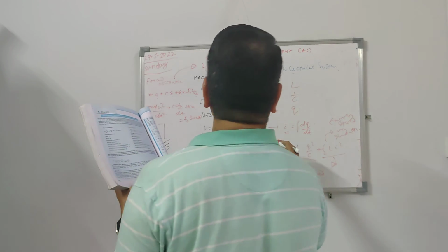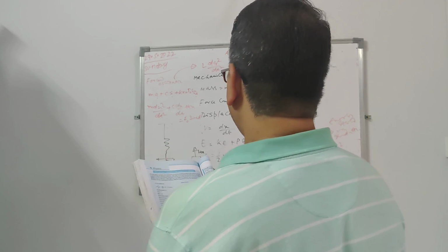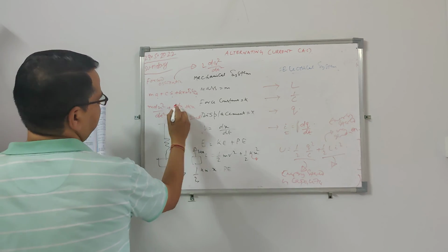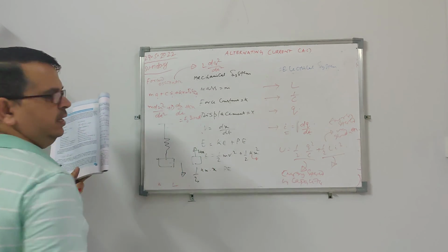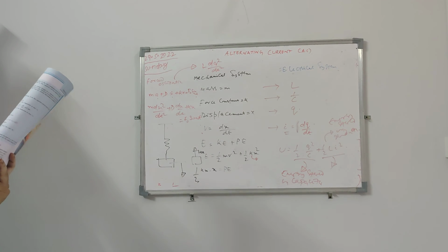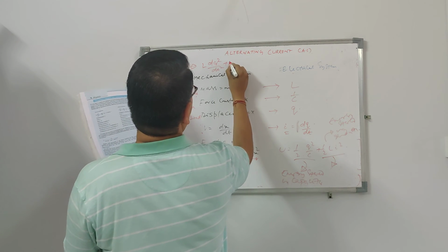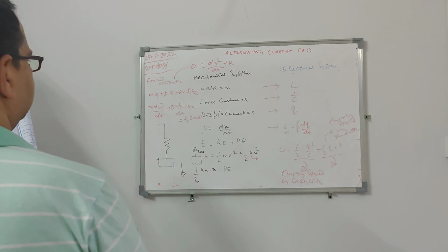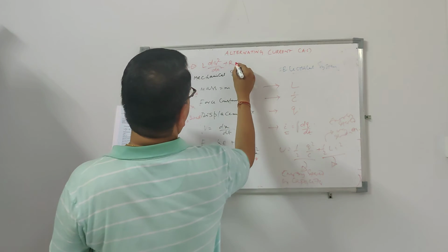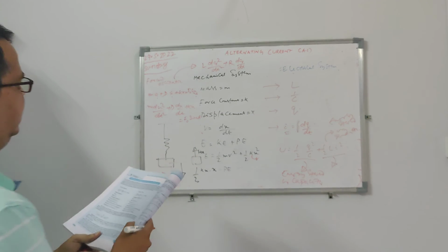Then damping is compared with resistance. You might get confused with capacitance, so you put damping as D. This damping in a mechanical system is similar to resistance in an electrical system. So here you can put it as R. Then the first derivative of displacement, so this can be written as R dq by dt.